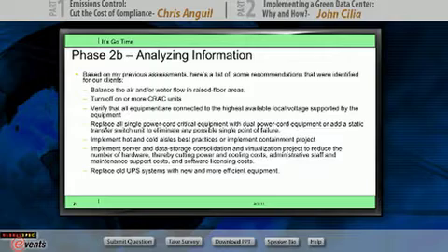You may want to implement hot and cold aisle best practices for your data center to be more efficient. You may have to turn off 1 or 2 CRAC units because you don't need them in certain areas of your raised floor. Okay, you want to verify that all equipment, for example, are connected to the higher voltage available for that particular equipment at your local site.